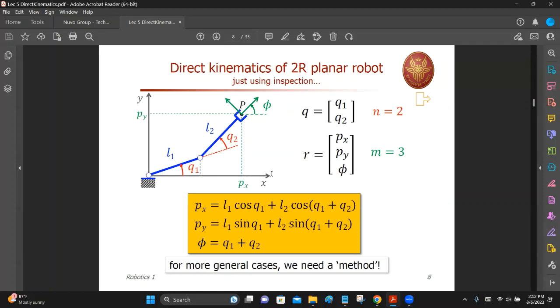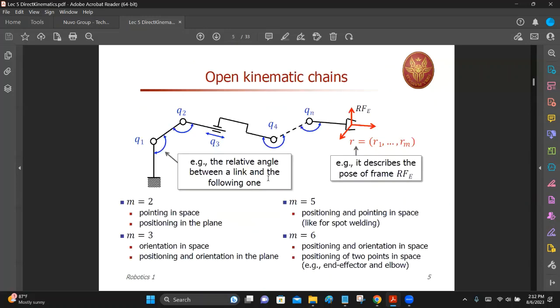So if I move back a little bit, here, this is the base. Sometimes you can call it link 0, that's fine, but this is the base basically. So the base has got to have a coordinate frame attached to it. Where do you attach it? Sometimes you say at this point, on the point on the ground where the base is attached, right? This is the origin, and then what is X? Maybe horizontal direction X, vertical direction Z, and into the board is Y, X, Y, Z.